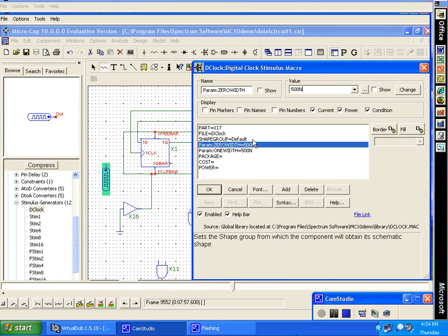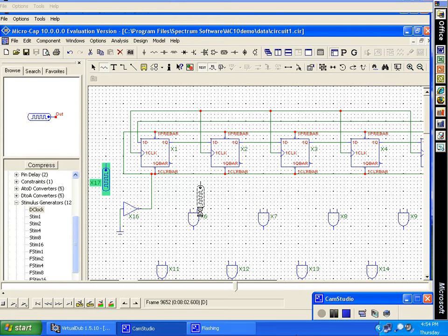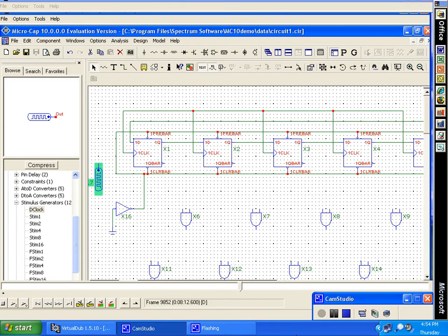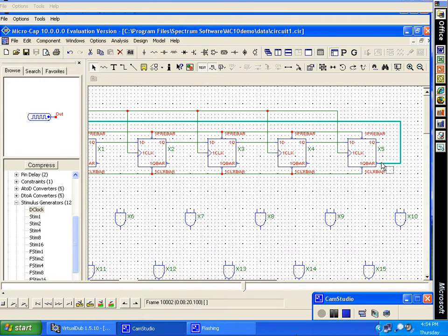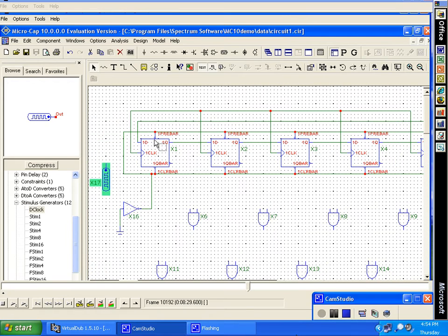We're going to tie it in and it's going to pulse all of these units. Now notice again, all of these are tied to shift ones in until the end. Then this goes high, this goes low, and a zero begins to be shifted in. So you go to the wiring, pick up that symbol, pick up the clock and tie the clock to all of the clock lines.